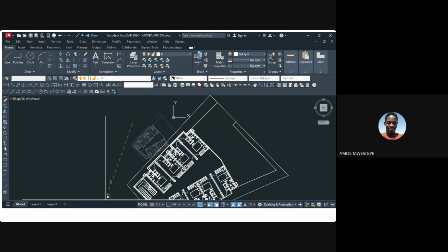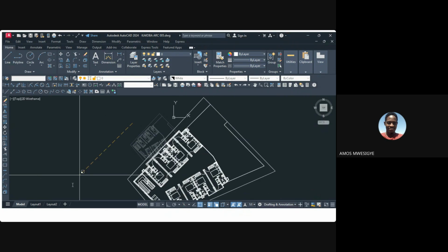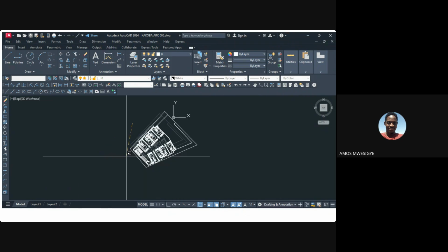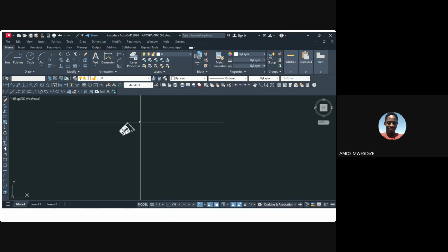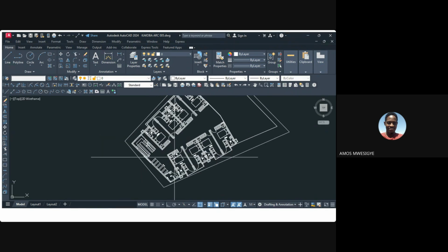It is already showing you specify scale factor. So we already have our scale factor in our RAM since we copied it. So when you paste it here and you press enter, you see it has made it smaller because we really wanted to make it smaller.